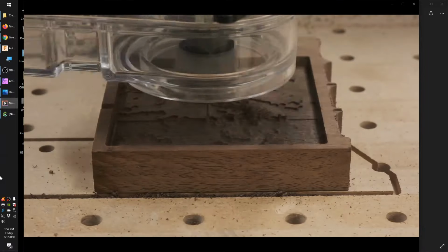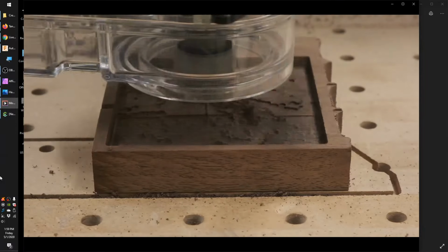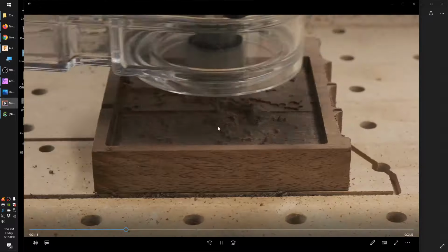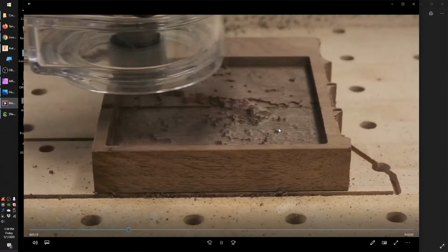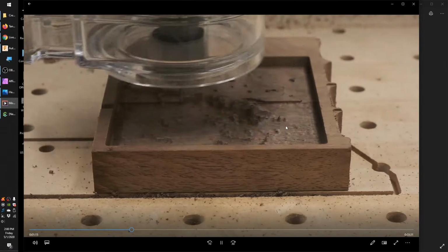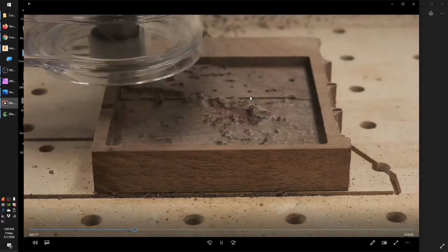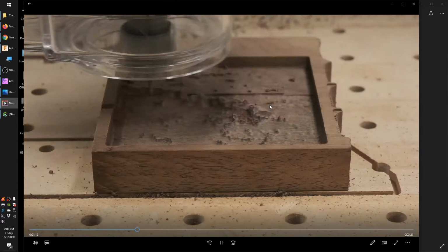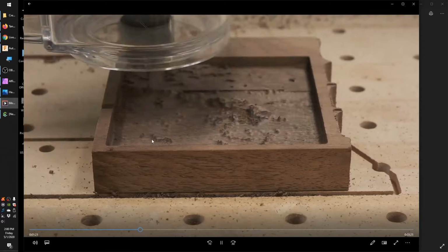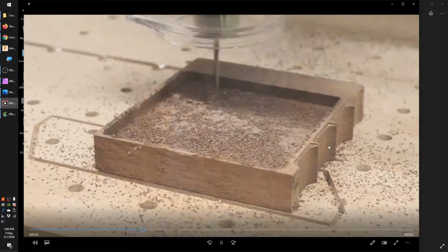And I actually thought about coming back with a 1/32 inch ball nose end mill just around the Hawaii portion, and I can show you guys how to focus a machining operation there, just because that's the only geometry that's going to be visible outside of the epoxy. So there's really no point doing everything in a super high resolution.